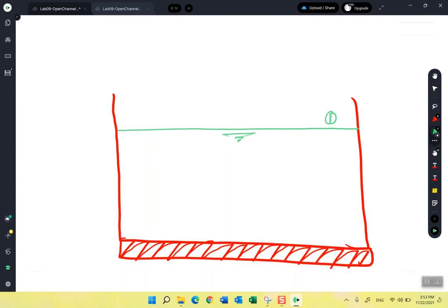You're right. This is related to the velocity, exactly, because when you increase the slope, you are allowing more water to fall more quickly. The Manning equation describes the relation between the driving force, which is the gravity, and the resisting force, which in this case is the friction.